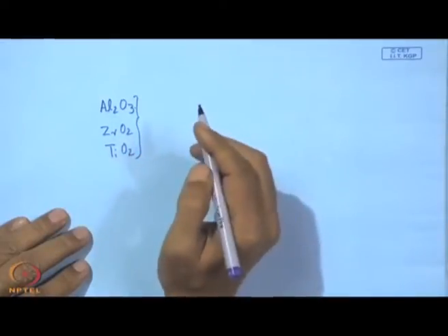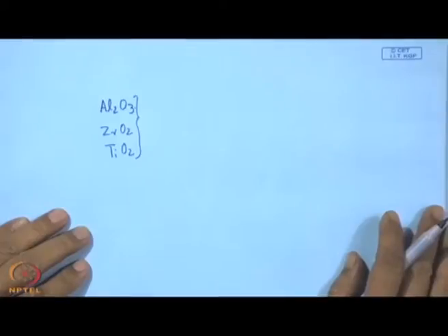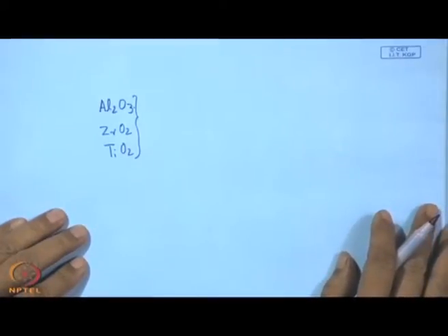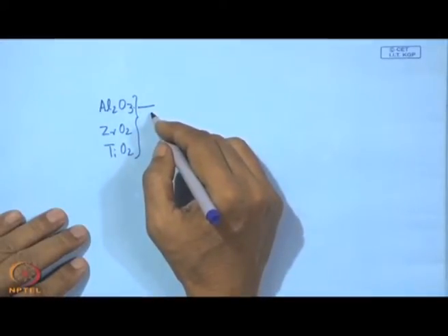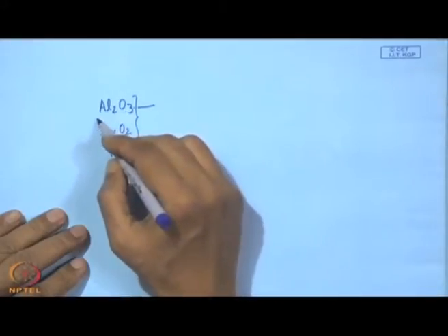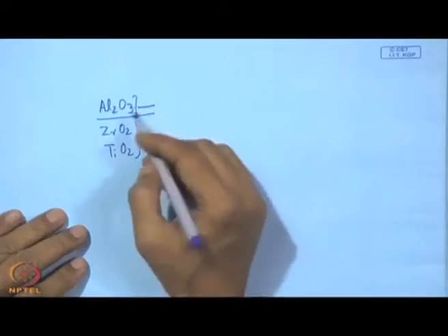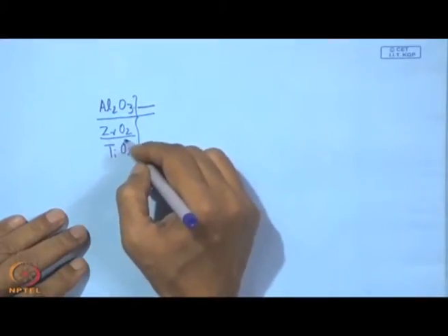So, these are some of the oxides which can be very useful and effective for improving the performance of many mechanical components which are used in areas where they can suffer from thermal damage and distortion. So, this heat shielding plus wear resistance, say for example, aluminum oxide, that is well known as a thermal barrier and also for wear resistance. We know this is also used as a hard coating in many wear parts. So, zirconium oxide, titanium oxide.